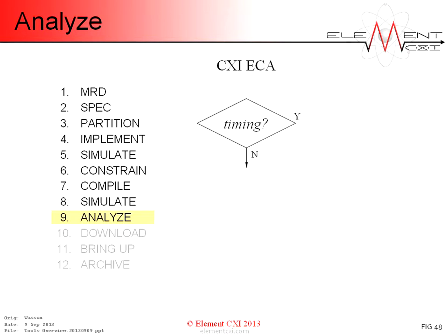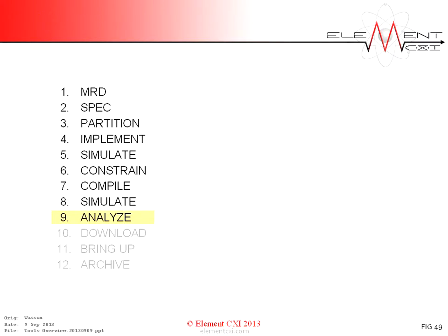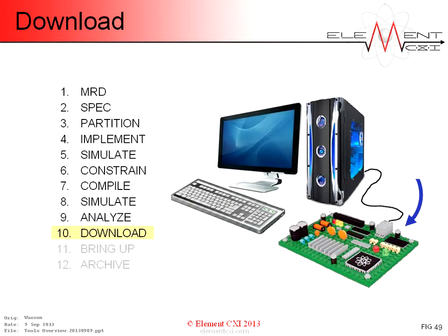Another timing failure class comprises design-related performance issues such as excessive latency, pipeline too deep, mismatched pipeline or slack, data streams misaligned, or inadequate bandwidth, insufficient computation in the allotted interval. Such issues might be introduced by pipeline insertion during compilation and necessitate a return to implementation. After all constraints are met, the design is ready for download onto a live board.